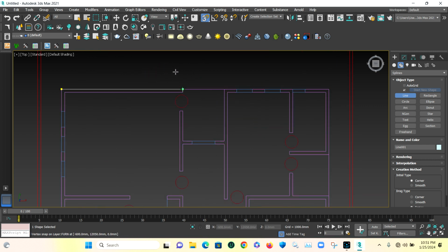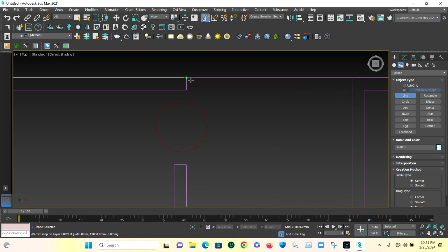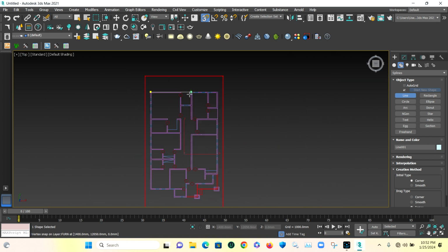You trace the external part of the drawing. While doing that, once you are working on a straight path, press and hold shift on your keyboard while you are moving. If you press and hold shift, you turn on a kind of auto mode. You just move at angles 0, 90, 180 on straight lines.